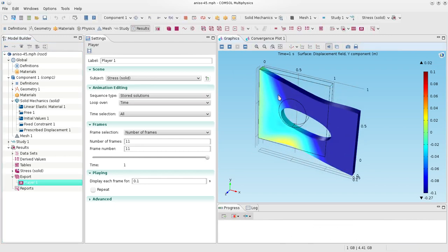And what's really happening is, as I pull, you may want to think about it yourself. One interpretation is that the fibers are at an angle of 45 degrees, and it's very hard to deform that. So to the extent possible, they are trying to preserve their lengths, and the way they preserve their lengths, if you pull in that direction, is if one tip of the fiber is attached to a point, the other tip moves down.